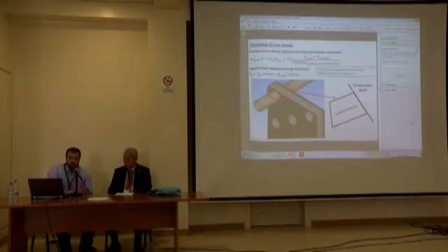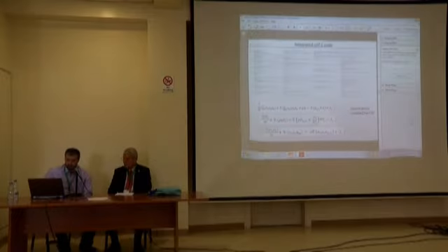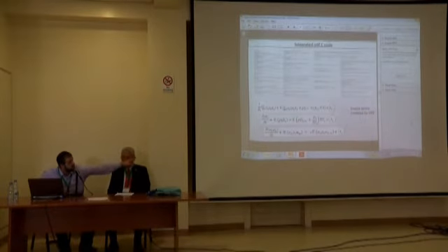Now remember that we're accounting for the condensation happening at the coil surface, so we need to model these effects. Here we used a fixed law in order to compute the condensation rate and accordingly the latent heat release. However, to do so, we have to modify the CFD code by building some user-defined functions, and here is an integrated C code that we have developed in order to modify these three sources that you see in the energy equation, species, and the volume fraction equation.